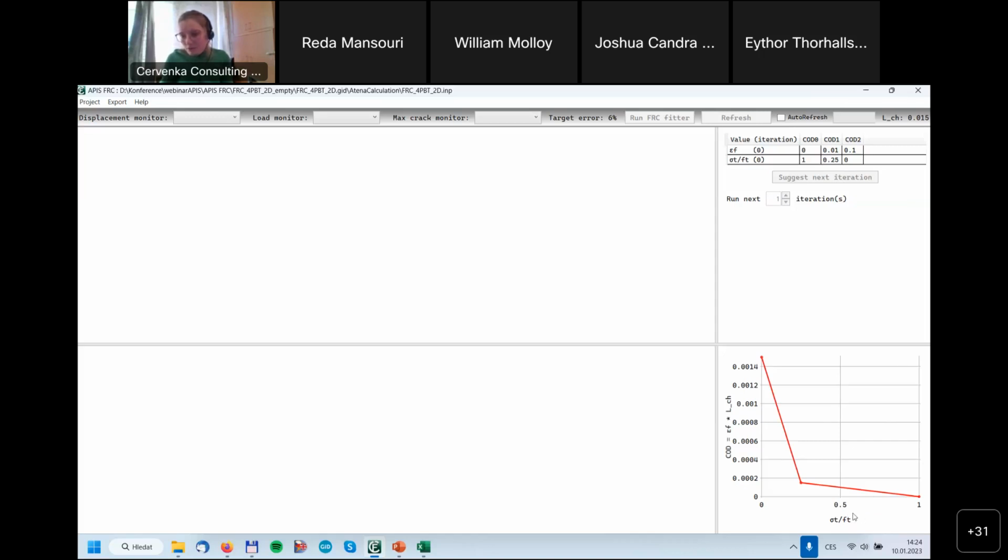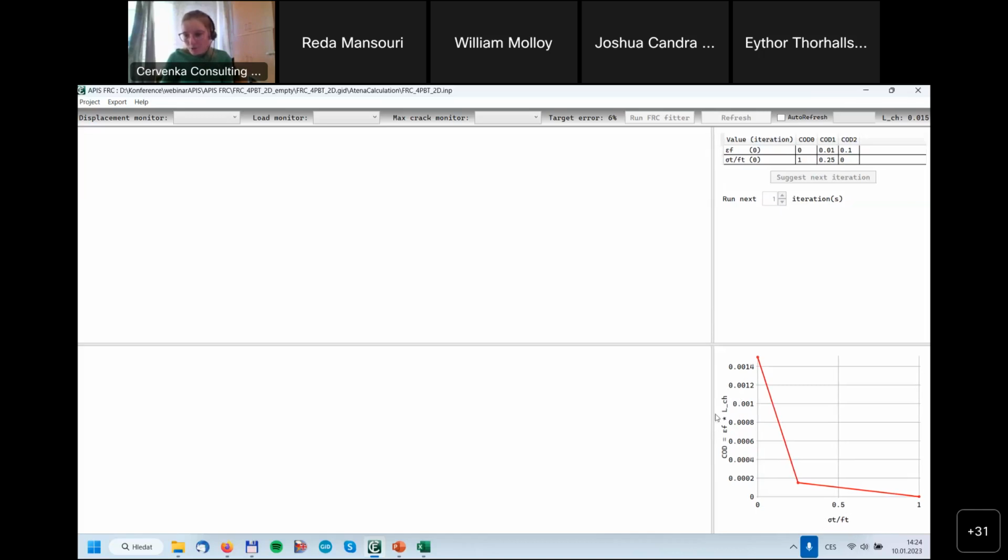Because as you can see, the stresses are in the X direction and the strains or the crack width is in the Y direction. It has its meaning because it will be better interconnected with other diagrams that we are going to load. So basically it's the tension function, just slightly flipped, and in this direction it's scaled a little bit, but the shape is the same.